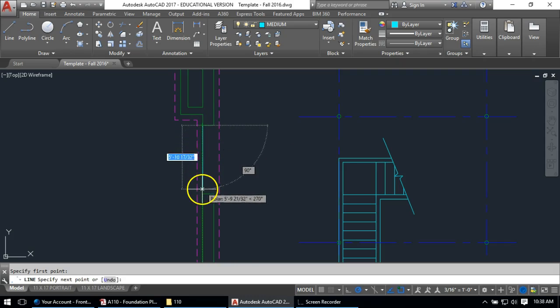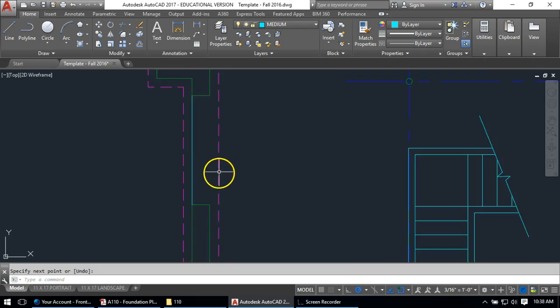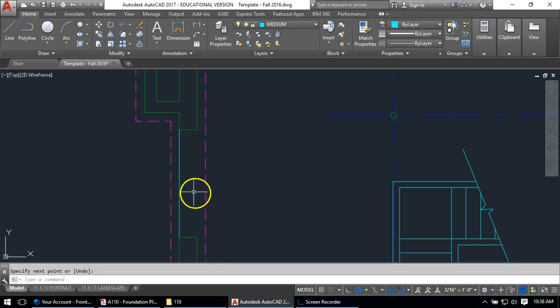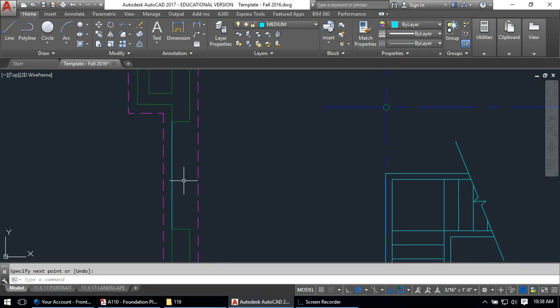So that one with the hexagon that's just off to the left of where I'm drawing, it's going to specify door information. That's going to talk about the exact size and type and probably give us more details about it. But since I don't have that information, I'm just going to estimate the door, and I'm going to do it as a polyline. And I'm going to assume probably a 6-foot door for a 6'4" opening, so each half is going to be 3 feet. And I'm going to assume that this one has a thickness of 1 3/4 inches. So that's what I'm going to do.